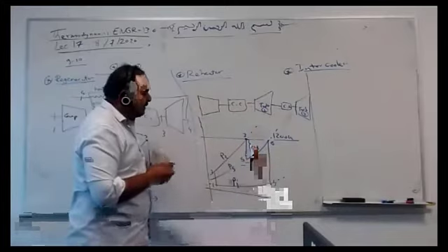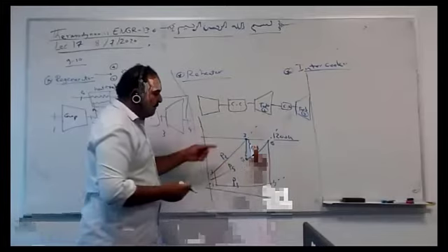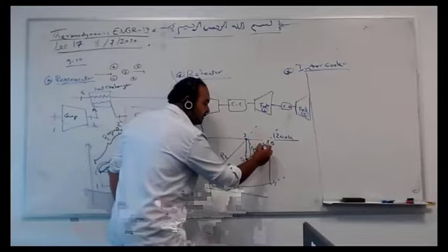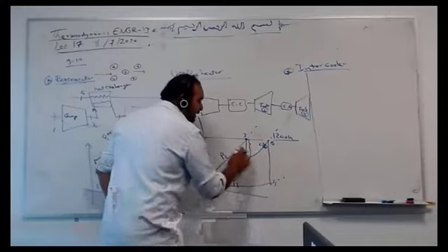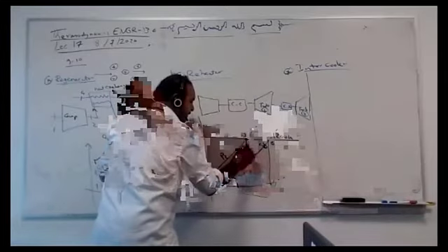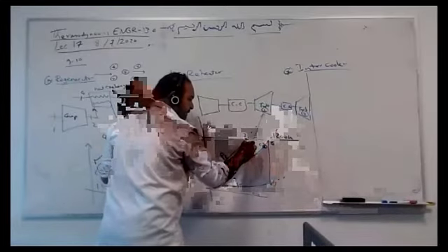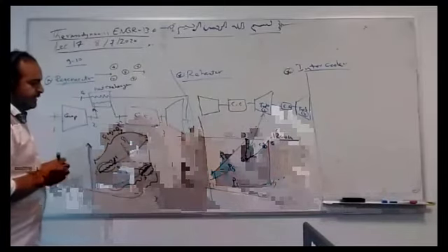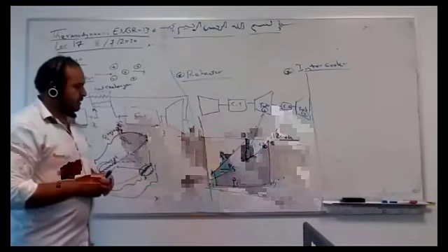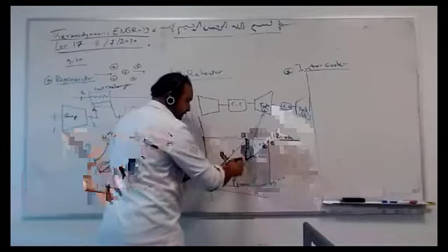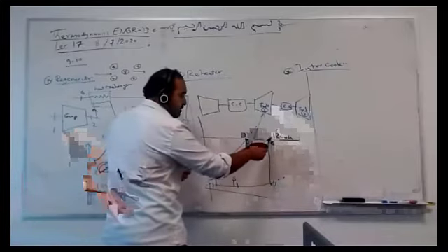Then I said, oh, how about this? Because the pressure lines are diverging, I'm lower than this limit. I can burn again. This is combustion chamber 2. So turbine 1, I make it, for example, green. I can get some work, let's say to drive the compressor, and get even extra work by burning again to go to a higher temperature.